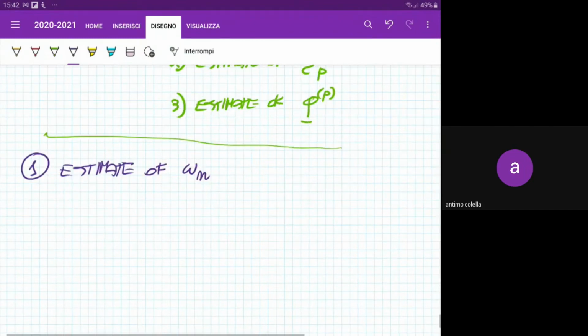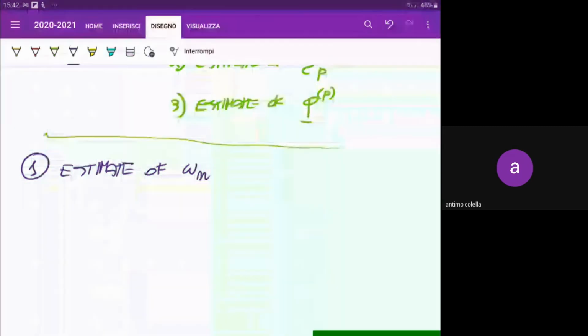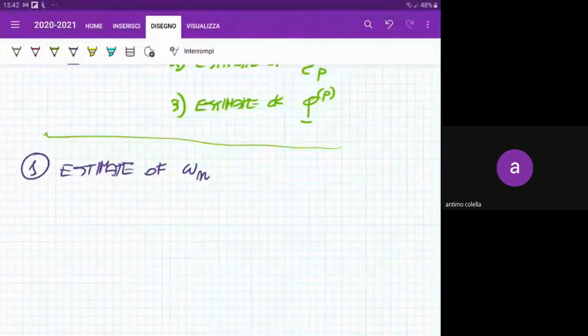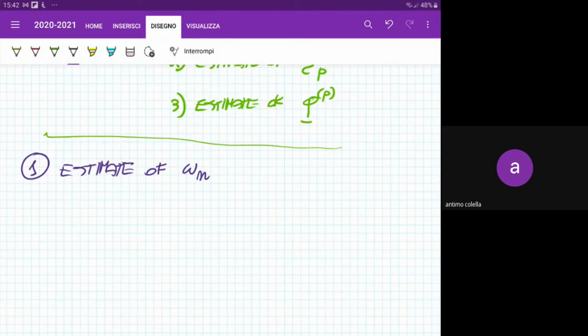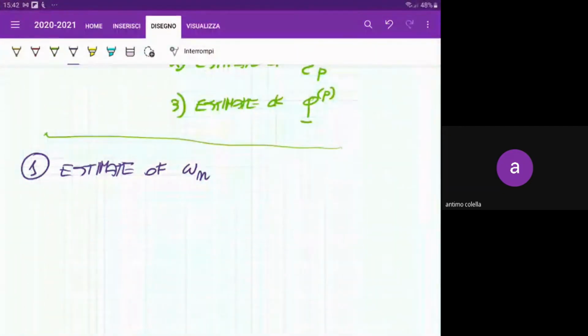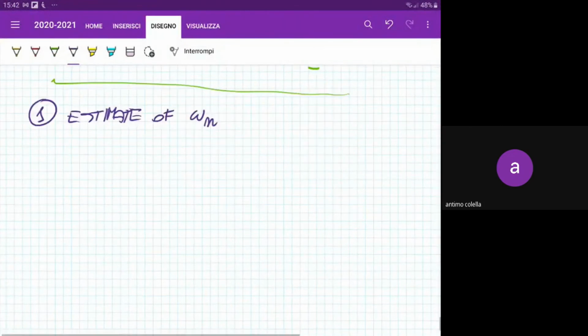We just have to check that the frequency response function at the natural frequency is characterized by the peak of resonance and the quadrature condition when referring to the amplitude and phase representation of the frequency function, or, but that's the same, we have to check that the real part of the frequency response function is crossing your omega axis, corresponding to a local maximum or minimum of your imaginary part.